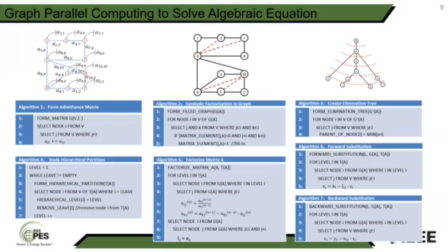So for admittance matrix formation, we can use nodal parallelization to perform the computing. But for factorization and substitutions, naturally their calculations are dependent from one node to another. However, it's not fully dependent. One node's calculation depends on just a small portion of the total nodes in the system because of the sparsity of power systems. So we use the elimination tree to determine the dependency.